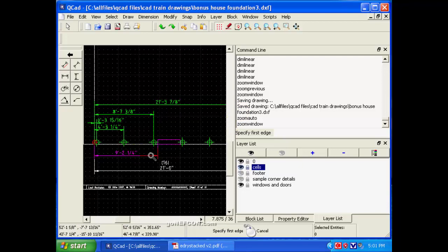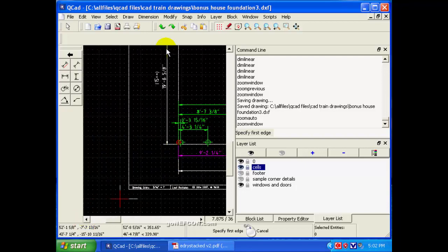So you may have to resort to putting some dimensions down here on the outside. But I would not eliminate these dimensions here. They're important. So then when you do the other walls, you got to put the dimensions someplace else. So you have to figure that out as you're laying out your original drawing, your initial drawing layout. You want room on each end or each side to place all these dimensions.